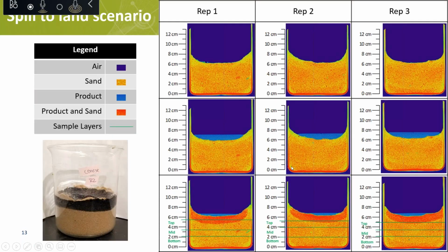Another CT example, just because it looks so nice. So this is a 2D look at product release to soil. We ran some tests on coarse and fine grained soil, and the question in this case was, in a cleanup of a spill of this material, would you be able to guide your equipment based on visual staining and impact? So it was looking at what kind of penetration depth we got from the product on the surface, and also once that was removed, if there were any other parameters that had leached into the soil beneath it.